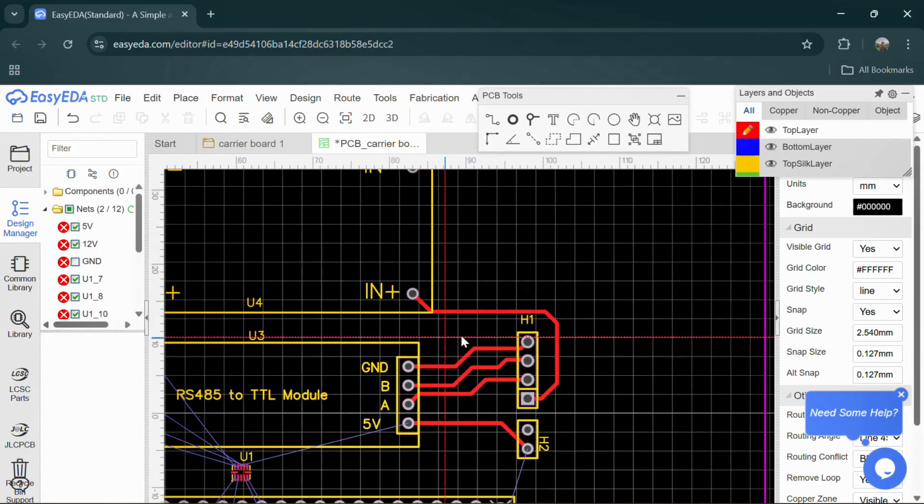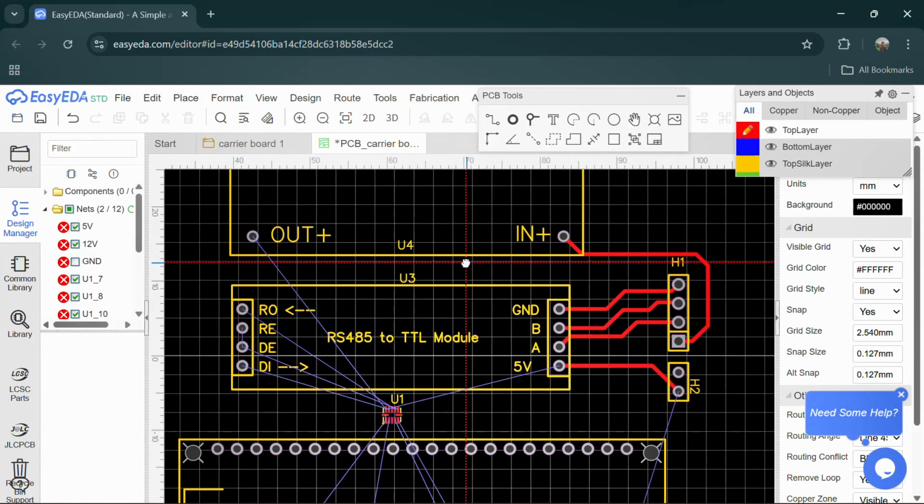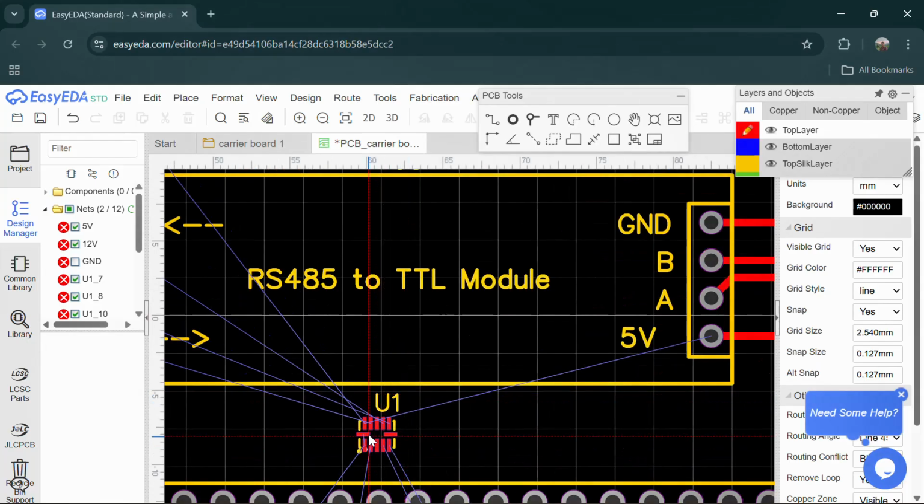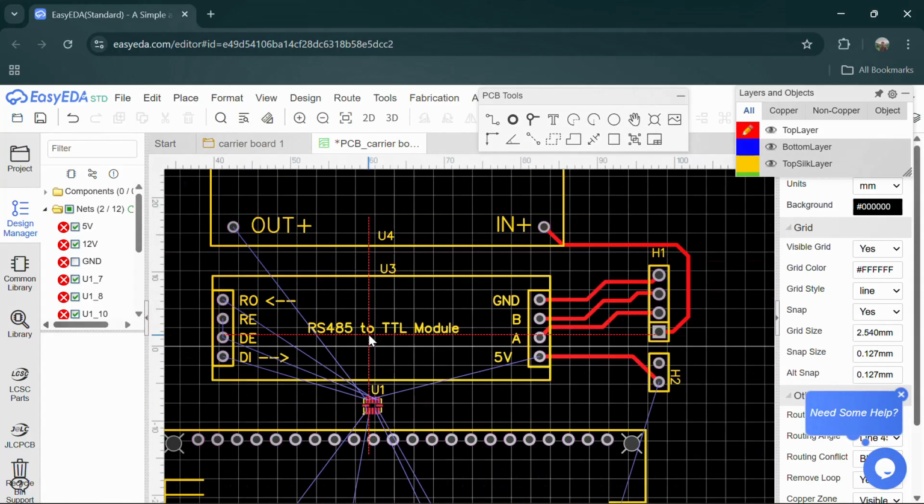Okay, so here this piece is converted, and then we will connect this piece into this, as we know that the blue out is going to there. Okay, so now what we will do, we will connect this 5 volt into this, because in the schematic the out plus goes to the 5 volt. So we will just make a wire from here and stretch it toward this, so this line is connected.